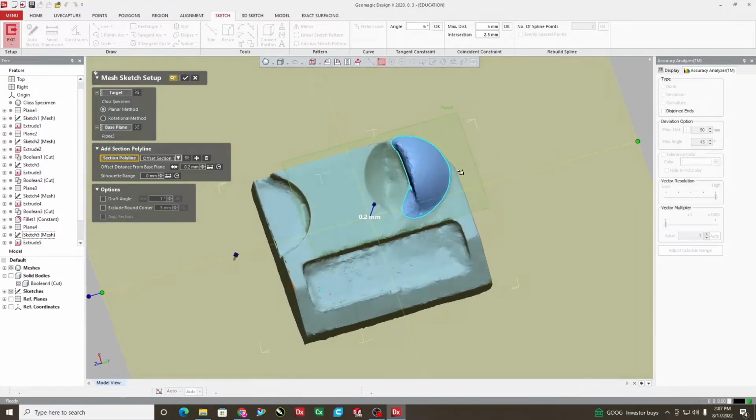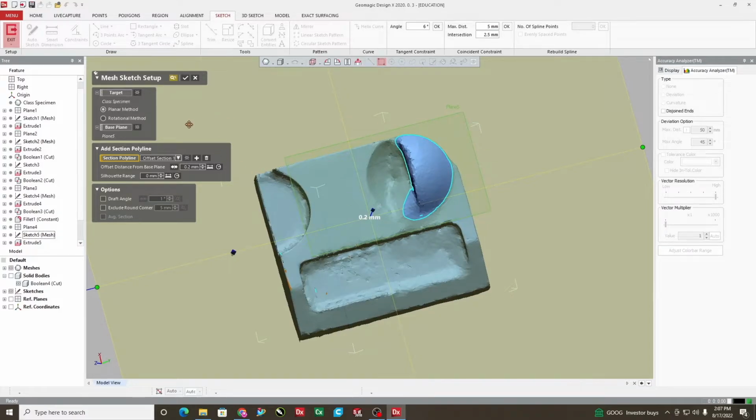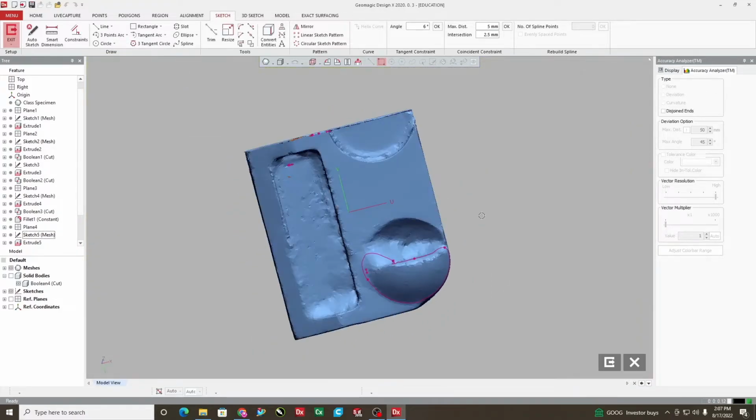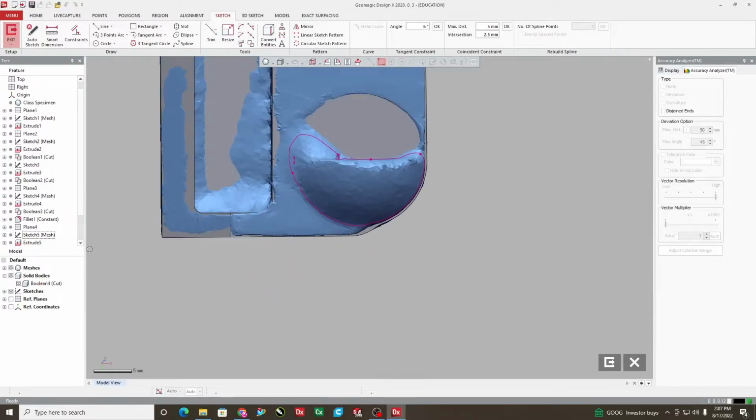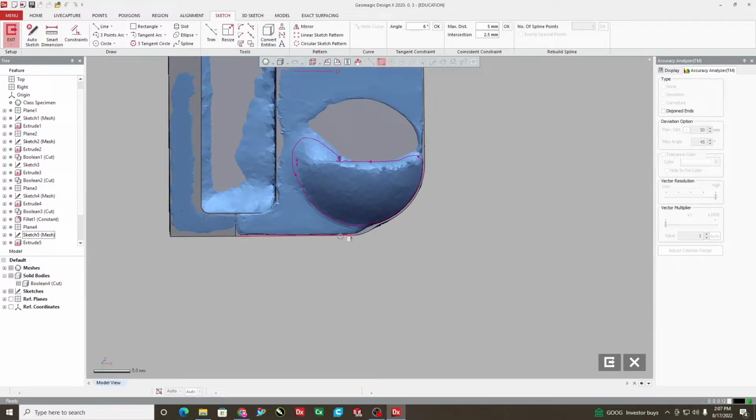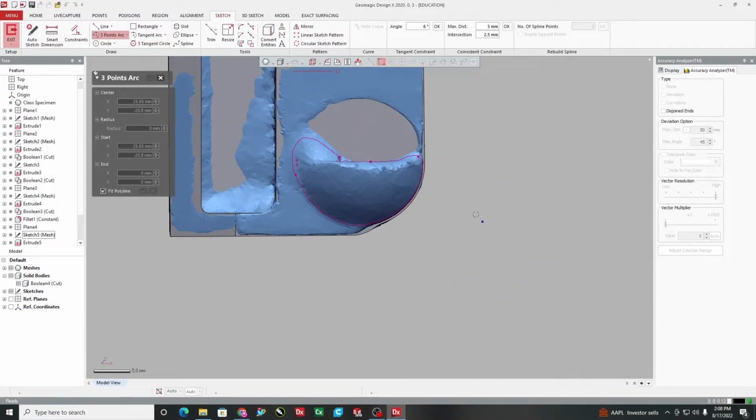So, it looks like it is a half of the total circle, it is a semicircle. So, we have created this kind of semicircle body. We will try to see how to generate a circle out of it, and we will try to generate the dome. So, number 1 is circularity, number 2 the dome, the straightness of the diameter of this circle. So, we have just selected circle from this sketch. So, we will just try to make a circle using 3 points here. We have selected 3 points and we are trying to fix a circle.